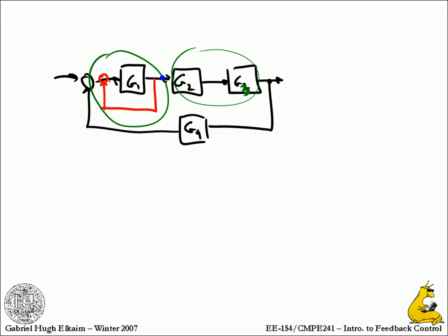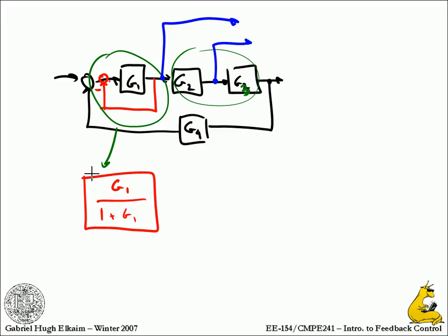Would it be too much to see the equation as you're talking about it? Okay, so this one collapses to, let's say this is negative feedback. That whole thing is going to collapse to G1, the forward gain, over 1 plus G1, which is the loop gain. So the forward path over the path all the way around, and then whatever sign this is, the opposite one there. So that's 1 plus G1. These two become G2, G3, like that.